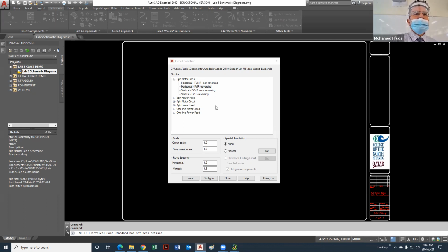We had a project where new gas compressors were added to an oil field, and when they came to commission the compressors, suddenly some submersible oil pumps tripped out. Why did they trip out? When they looked around, they said, "Oh, there's a voltage dip." What happened? Well, it's because of starting the compressors. The compressors were started direct online. They pulled the voltage too much.